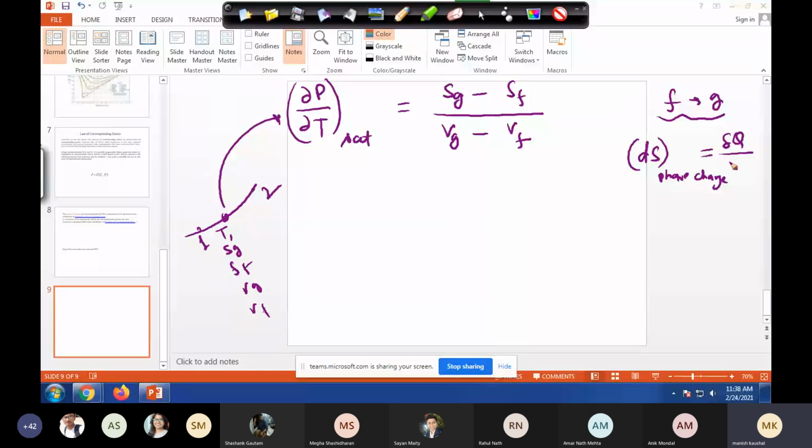Okay. So dou q by instantaneous temperature at constant pressure, that we know. Of course, temperature is also constant. But what we know that dou q at constant pressure is equal to? Anyone? dH. You just write dH by T. So basically, along this saturation line, since everywhere it's a phase change, Sg minus Sf, we can simply write Hg minus Hf by instantaneous temperature.